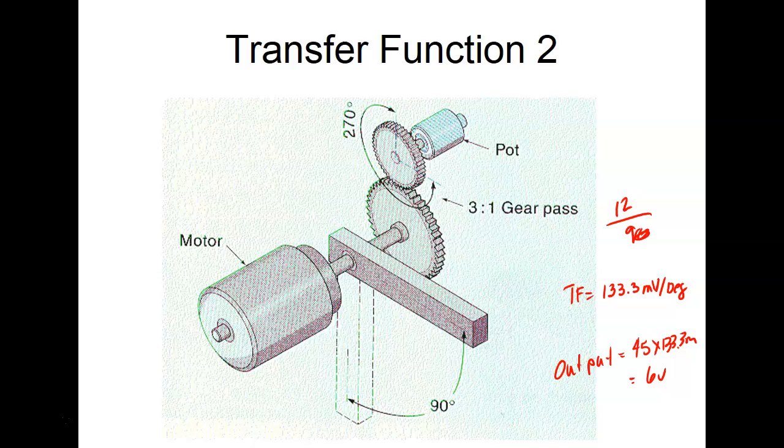Here we're not going to talk about analog outputs because what we're doing is sensing position. So I bring this into my control system, and my control system would have to translate 6 volts into 45 degrees. Now you could calibrate a meter with a resistor to do that.